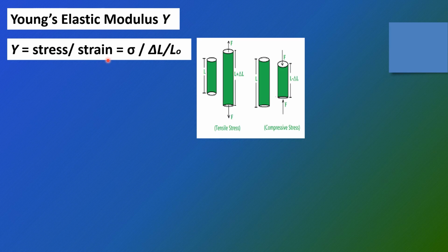So, when you say strain, we are referring to the ratio of the change in the length over the original length of an elongated material. This is particularly true for a kind of stress known as tensile or compressive stress. So, if the kind of stress is tensile or compressive stress, the corresponding kind of strain is also known as tensile or compressive strain,